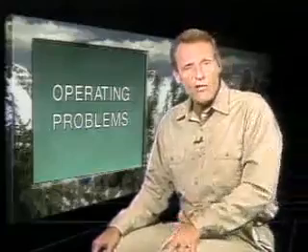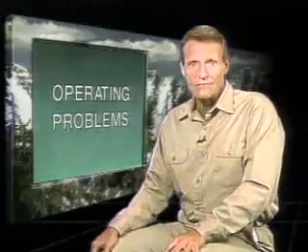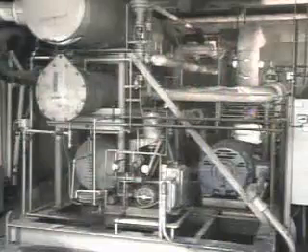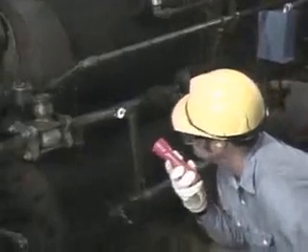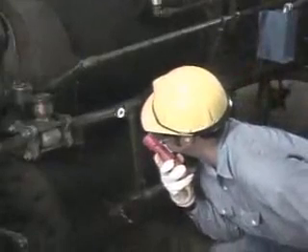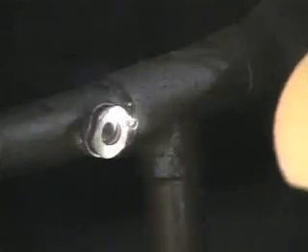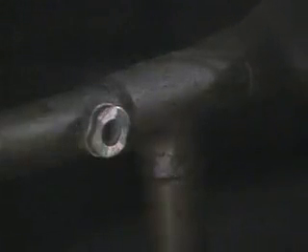Ideally, a vapor compression refrigeration system will run efficiently and practically by itself. Sometimes, however, problems may occur. One of the more common problems that can affect a refrigeration system is an improper amount of refrigerant. The amount of refrigerant can be determined by checking a level indicator on the receiver or by checking a sight glass on the receiver outlet. When the amount of refrigerant in the system is correct, the refrigerant seen in the sight glass should be clear. If there's not enough refrigerant, the refrigerant may appear cloudy and it may contain bubbles.